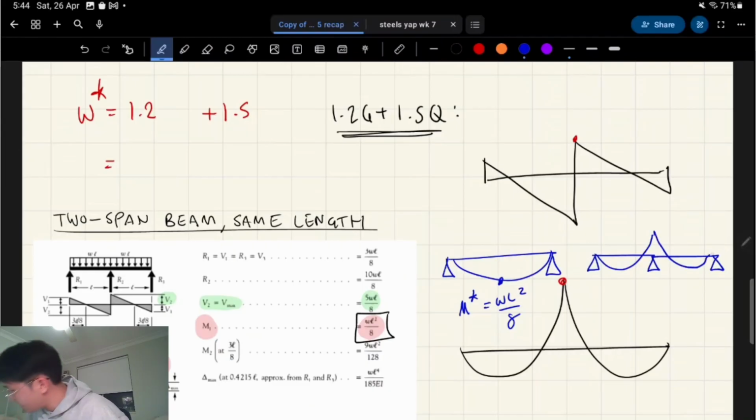But do you reckon that the maximum bending moments in the middle of those spans are less? If you think yes, you're correct. There's less of a positive moment, but the maximum moment will be over the middle support now.